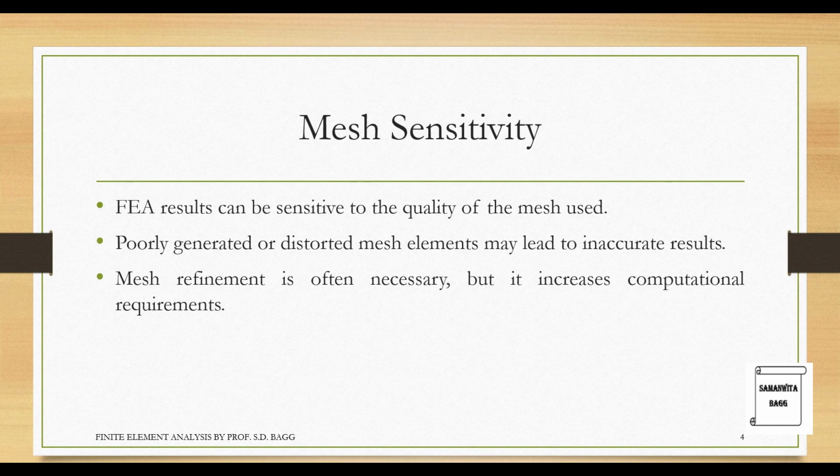But when you increase the number of nodes and elements, the device that you're using for running the software will take a lot of time to give you the solution. So in that case, you need to have a very good, high-end processor, or it will take a really long time and sometimes the PC even hangs for a real long duration. So computational requirements are very important when you talk about good meshing.